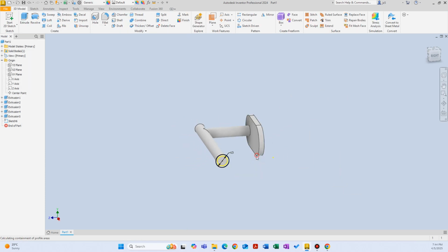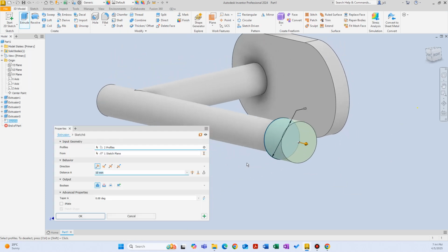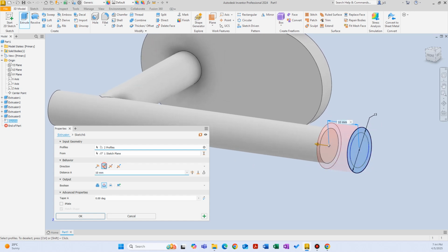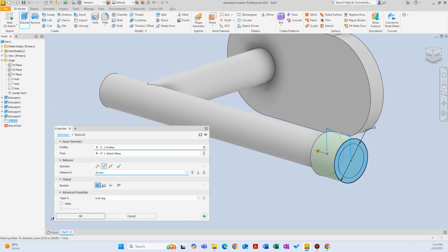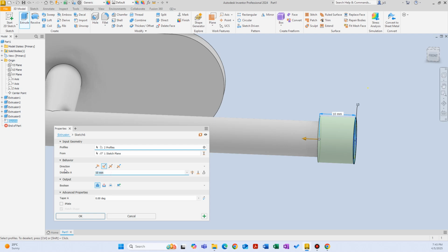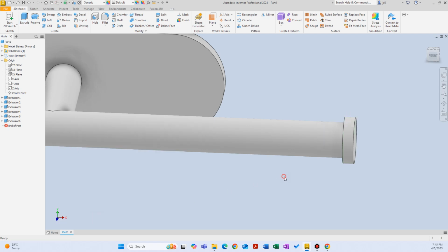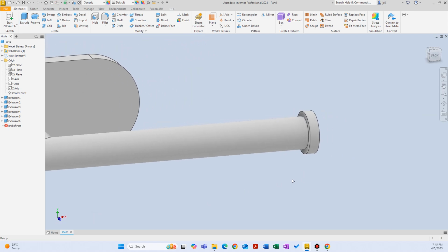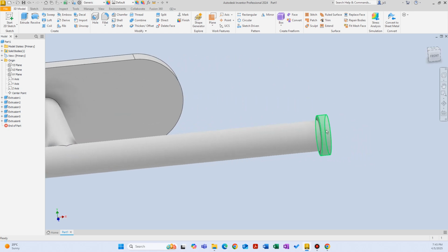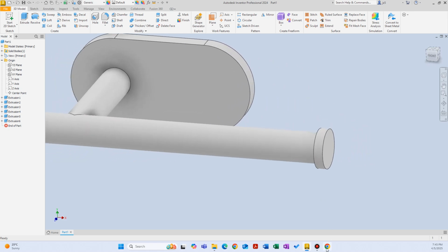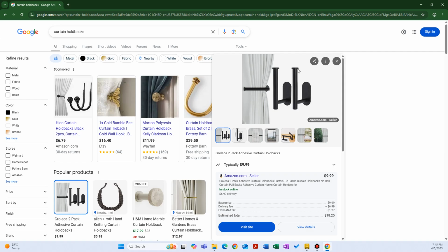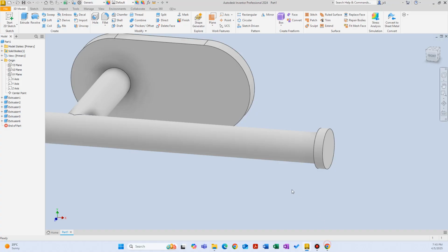And then let's right click and click on extrude, and let's switch the direction of it, and we maybe 5 millimeters. Yeah, 5 millimeters should be enough, or maybe just 3 millimeters. Okay, yeah. So we just added some material backwards this time to have that step on the top side.